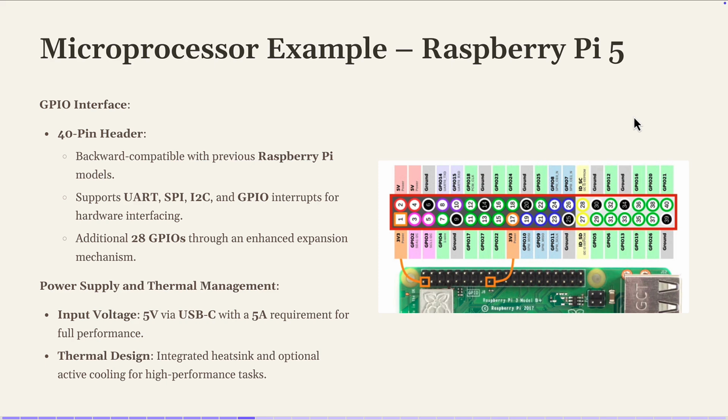This is a power port. This is an SPI port. So this is another type of interfacing. So not all these ports are the same. And usually when we work with embedded devices, you have to look at the data sheet. What does each port correspond to? It's not just plugging a wire here. You can just burn it out. You can burn your sensors or provide the wrong input or output. So it's really important to have a full understanding, because software engineers usually don't care about this stuff. So they just plug their things in, go to the coding, and then they burn everything out. There is a data sheet with every control board that you need to understand at a low level.